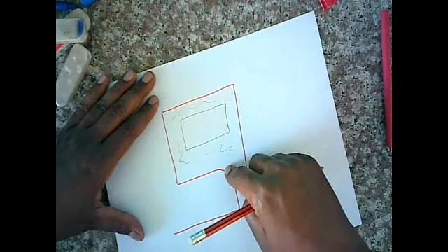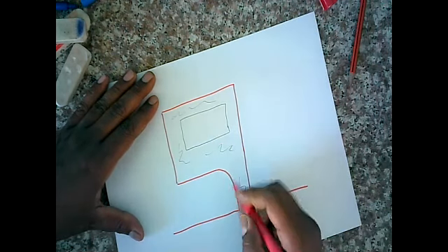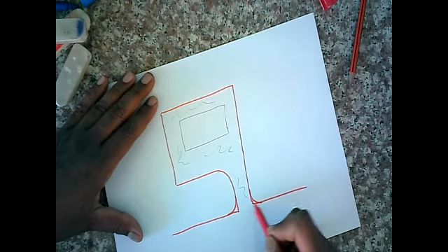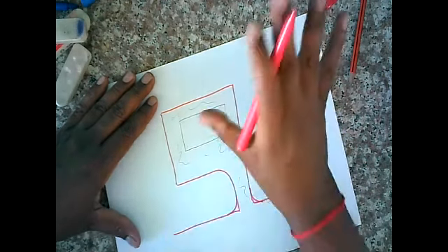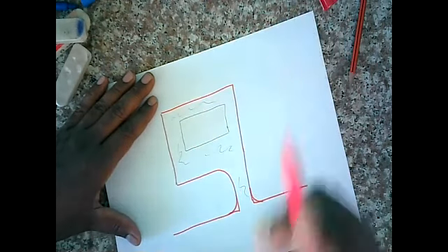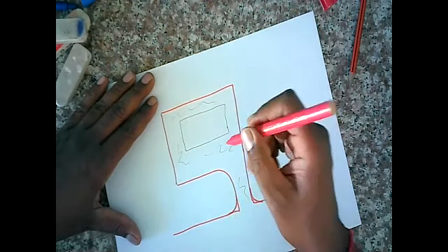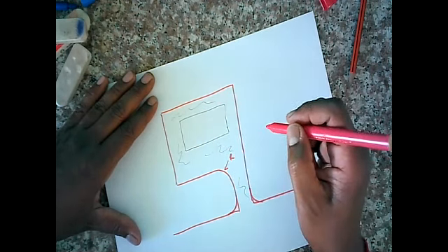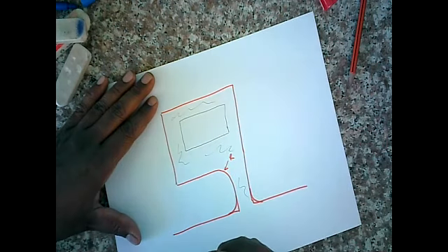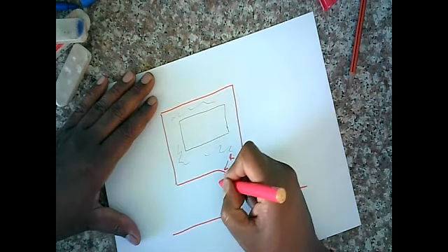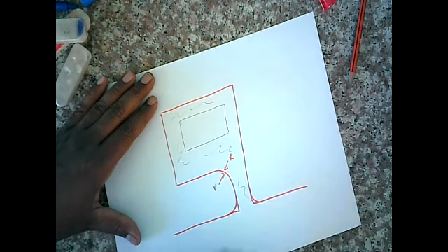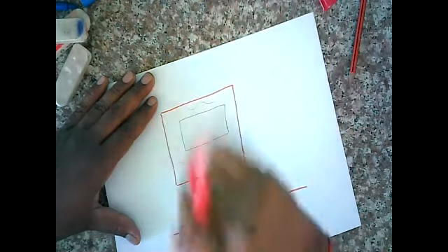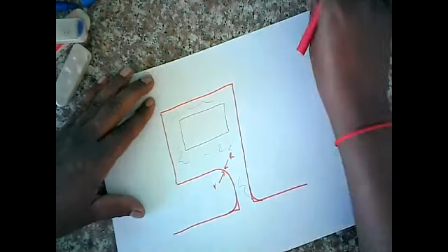Right? Quantifying those corners, and maybe this was incorrect. Maybe there's a fishtail there and fishtail there. So there's more corners there on either side. Also be very careful. Observe the arrow. Is it on the inside or the outside? Right, because this arrow direction makes a difference, isn't it? Am I giving you the big radius or the small radius? Something to look out for in small print.